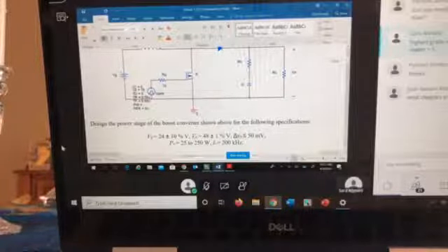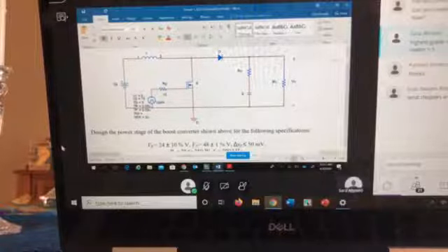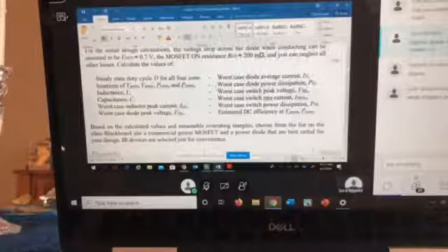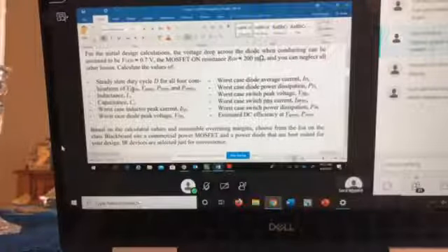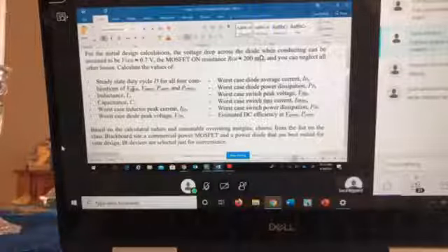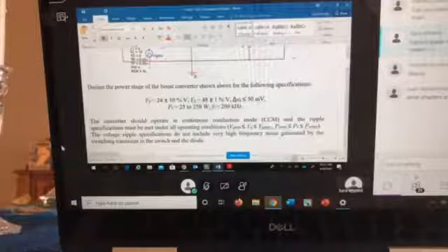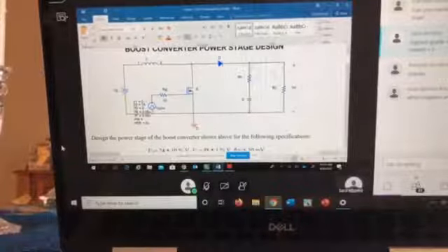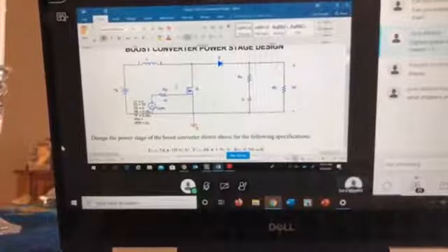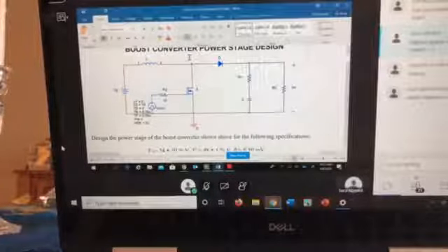But I have to see. So when we said like here, what are we gonna do? It asks you to do a calculation for all of this. It says all the 4 combinations. Again, what is the 4 combinations? Your 4 combinations is your operating range. Operating range, what can change? Input voltage and output power, which is your load. So if I'm changing this and changing that, I want to make sure that whatever I designed for in the rest of the converter needs to all be satisfying this.